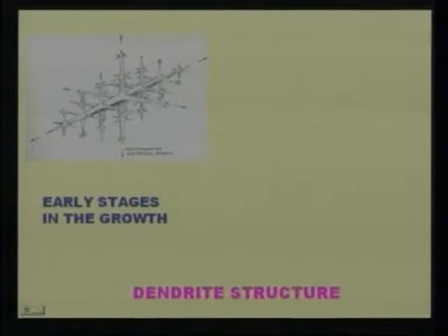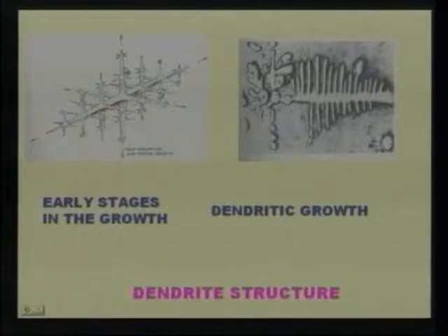When a pure metal solidifies, each crystal begins to grow independently, that is, from a nucleus or center of crystallization. Nucleus is the simple unit in the crystal lattice. The crystal develops with the addition of atoms according to the lattice pattern, and rapidly a visible dendrite or a tree, you can see now a tree. Why is it called dendrite? Dendron is a word from the Greek. The meaning of dendron is tree.